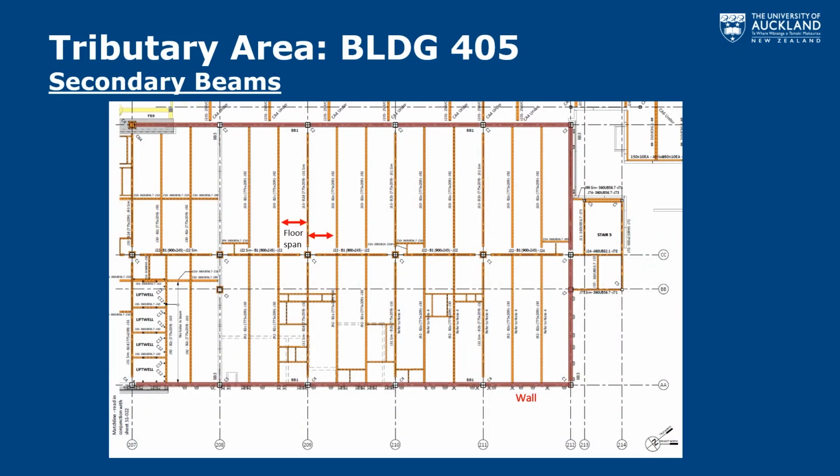So if we zoom in on that area which we had highlighted, a few things to help orient yourself, referring back to the photo we had just seen. This is on the second floor looking down; if we were on the first floor looking up, we would see the same framing. As you saw in the photos, the floor is spanning in this direction, roughly north to south. On the upper stories, there are just columns and primary beams, which allows you to have lots of nice windows.